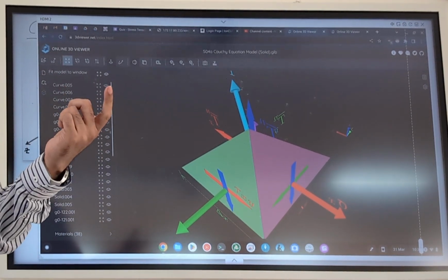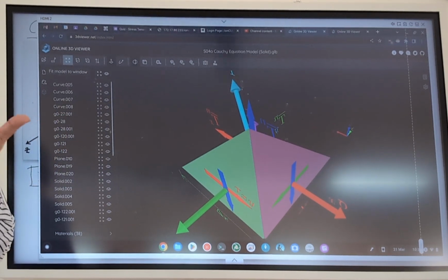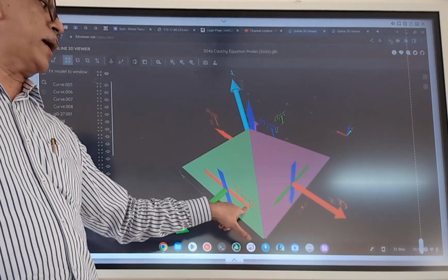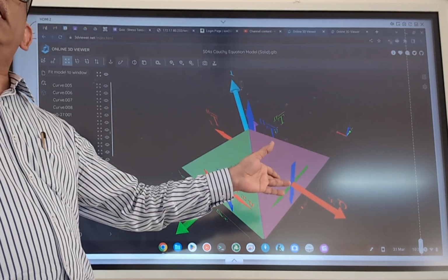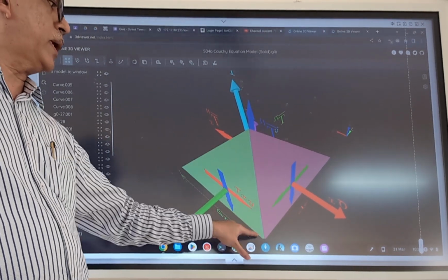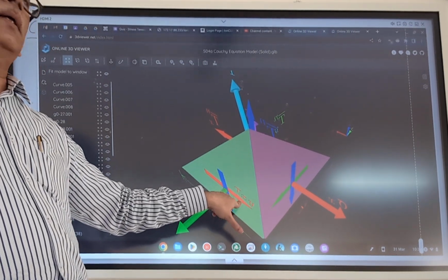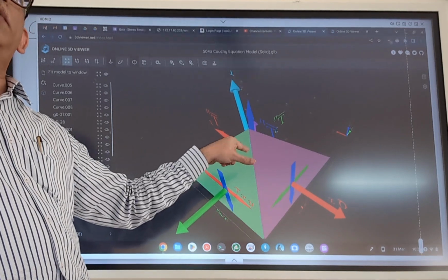So that is some property of these shear stresses. It is the equality of cross shear stresses. Very good. So that is the reason that it is written here as tau xy. So this is the component which only contributes to the forces in x direction. So let's call this particular area Ay. So Ay multiplied by tau xy will give you the force in the x direction, the contribution from the y plane.